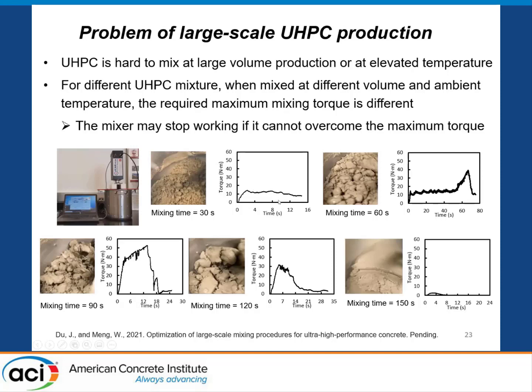But when the concrete turns into clumps, the mixing gets very hard, because, as you can see, the required mixing torque jumps significantly. In our case, when the mixing time was 90 seconds after water addition, the mixing torque reached its maximum value.